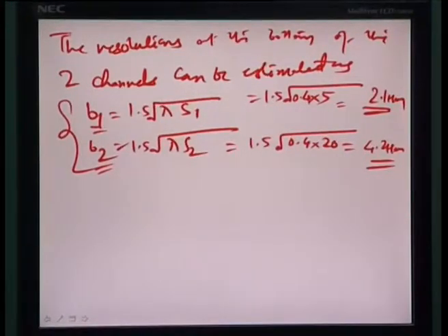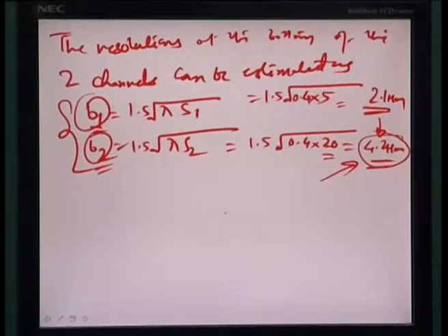So, just by going about 4 times more on the depth, you have already lost the resolution by almost 50%, and you only realize a higher minimum feature size by going deep down inside the channel. So, this is a potential problem. In photolithography and in contact lithography, if you go to higher channel depths and try to do resist processing, you will always end up with a lower resolution, and this has to be somehow controlled by guiding the light in a manner that diffraction does not happen in the whole process of exposure.